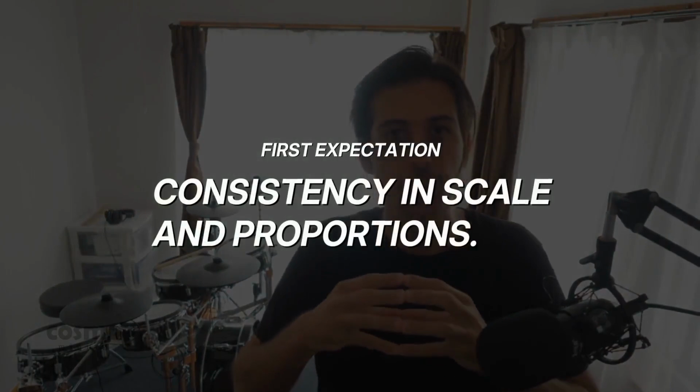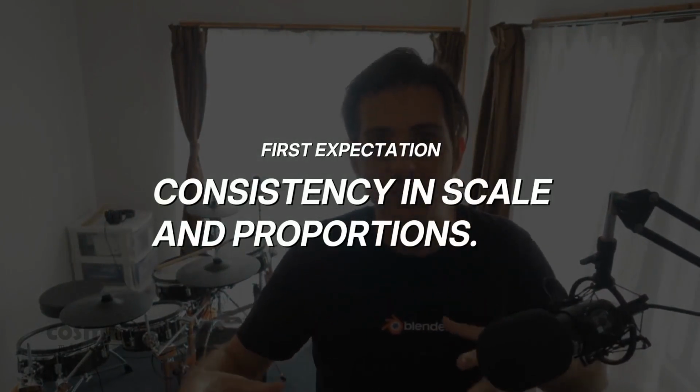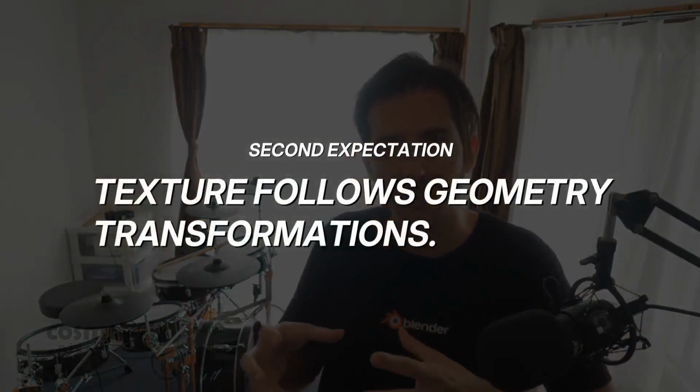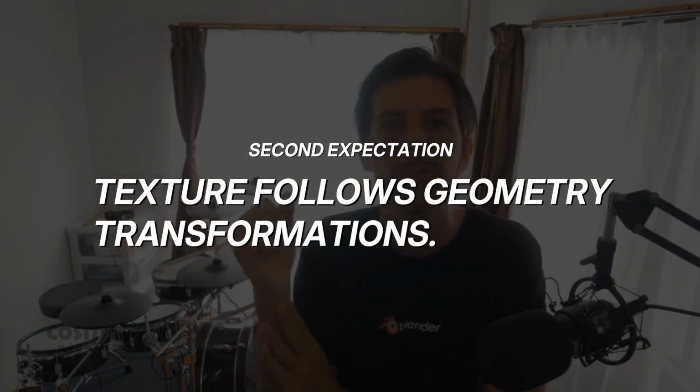exercise. Let's imagine that this is going to be our first time assigning materials to multiple objects in Blender, okay? There are two things that I would expect if that was my first time. The first was that the texture would be consistent. The proportion and the scale would be consistent across all my objects that receive this material. And the second one, my animated characters that distort, that are deformed, the texture would follow these transformations and give me the impression that the texture is applied, attached to the surface.